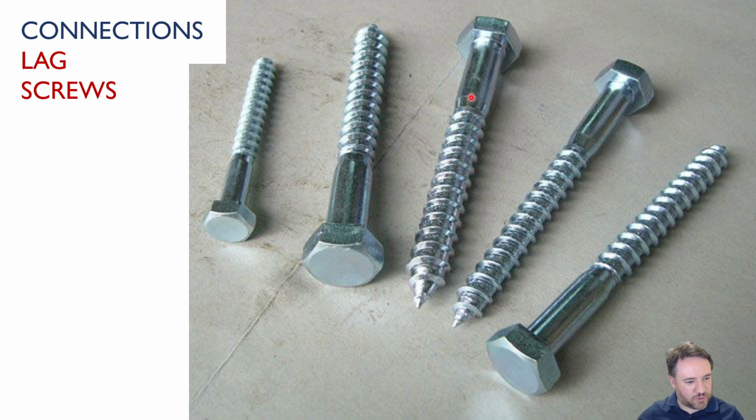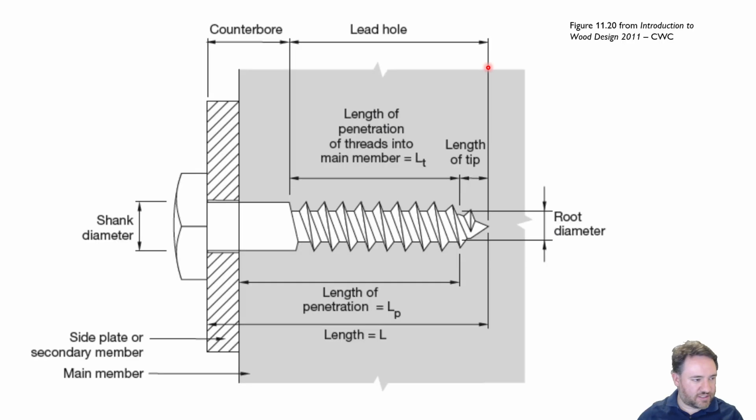This is the part that's supposed to be intercepted at the interface, right? So you can see there's a shear interface here between the steel bolt and the wood. One is going to move relative to the other, obviously, is the whole idea of this connection. So let me show it so that you can see the steel side. The steel is going to want to move relative to this, and that's why I'm putting the bolt here, right? Is to prevent these two from moving relative to the other.